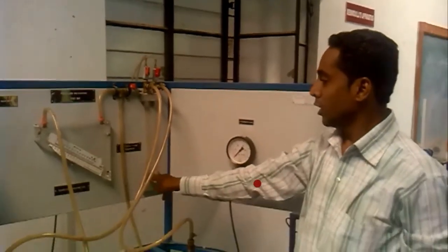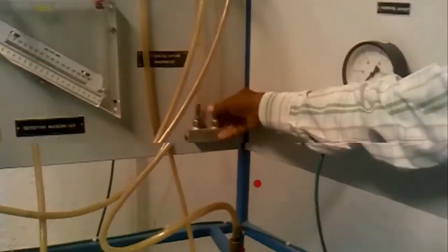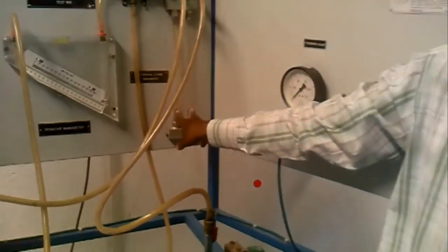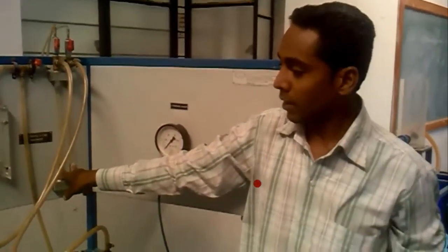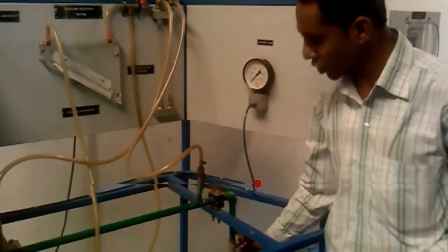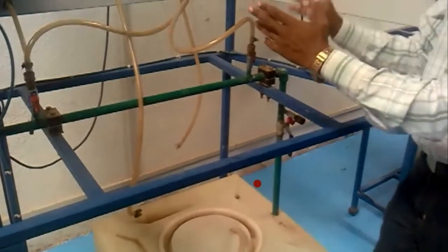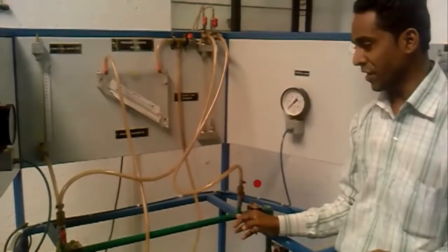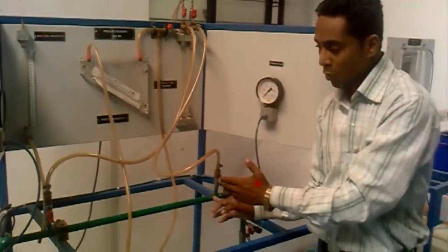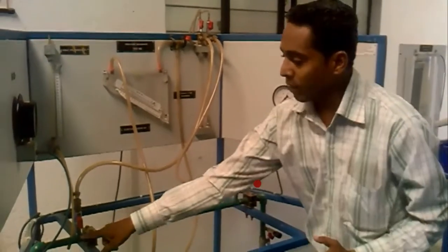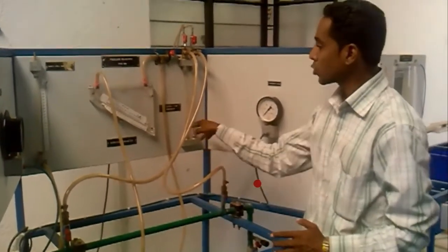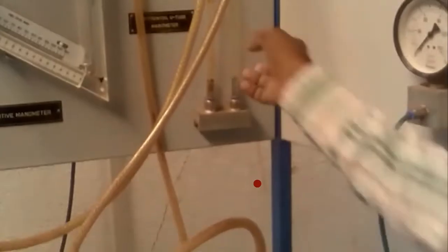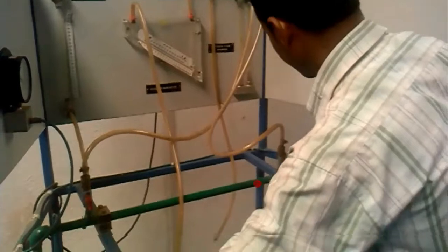And here is mercury. Initially, if there is no pressure in the system, both levels will show the same reading. However, I will increase the pressure in the system. These two ends are apart by, suppose, 1 meter. Delta P between them will be shown here in terms of height. In terms of height means how? You will see.